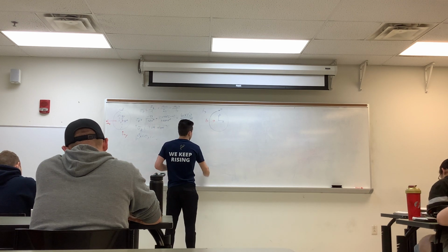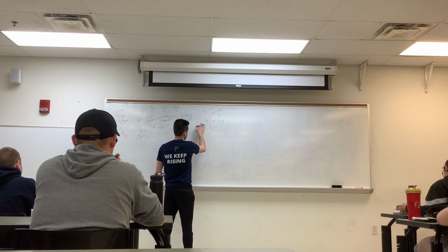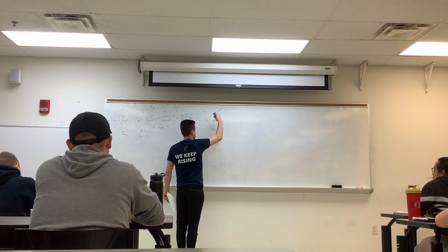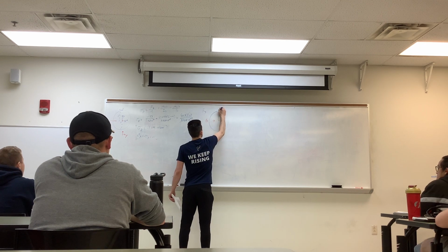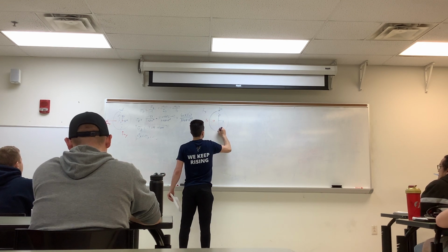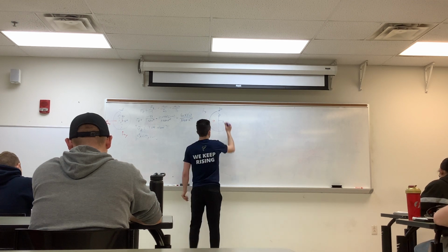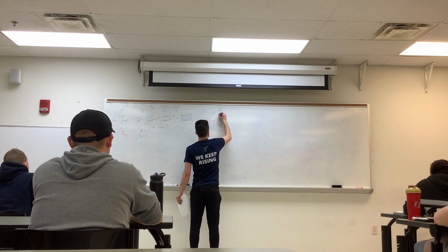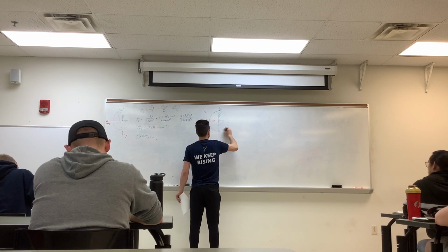We're looking at point H, so as it's going from left to right here, when we find our shear flow, we take a cut across that section where we're looking, and then we take everything above it, so in this case it's to the right, everything over here, which will correlate with our shear flow.